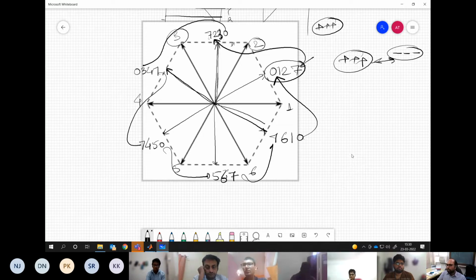Do you see that? So the first thing we have to avoid is any multiple switching, which is avoided by having the same 0 vector applied in the next sector in sequence. We do not change the 0 vector abruptly. We continue with the same 0 vector.